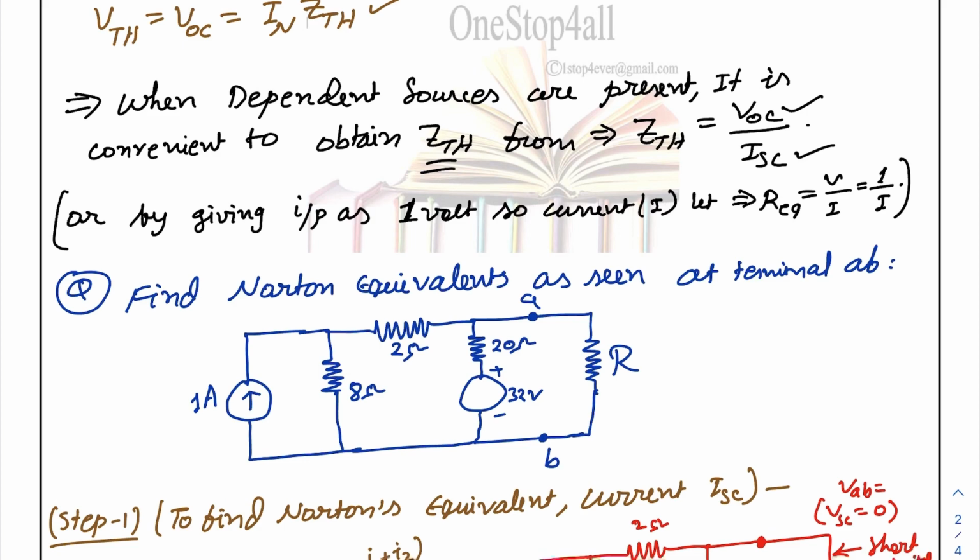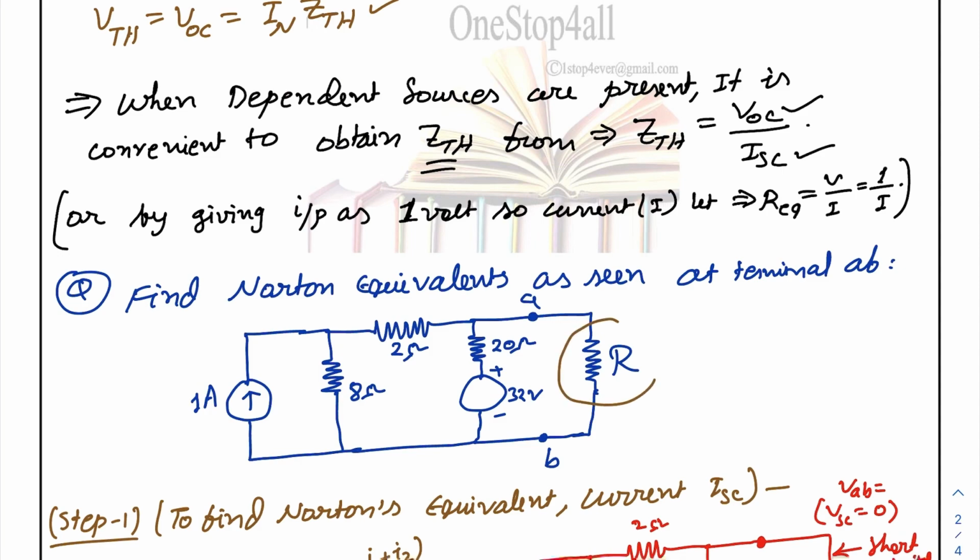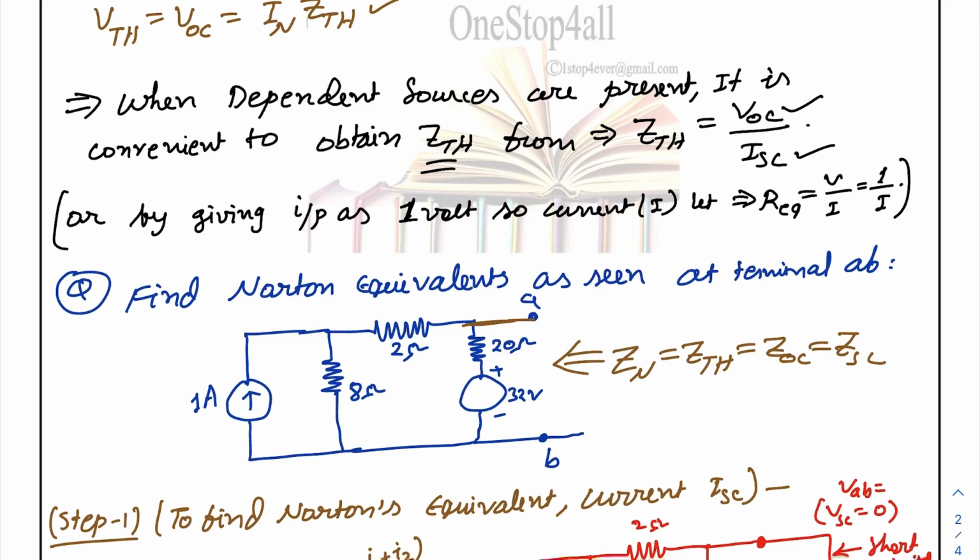जैसा हम लोग ने प्रीवियस लेक्चर में सॉल्व किया है, जो हम लोग ने थेवेनिन इक्विवेलेंट निकाला है, कैसे निकाला था याद है आप लोग को? इट इज़ सिंपल. वी विल रिमूव दिस वन, इसको ओपन सर्किट कर देना है, ठीक है. और यहाँ से ये ZN बोलो या ZTH बोलो या ZOC बोलो या ZSC बोलो, ये सब एक ही टर्म है. नॉर्टन इक्विवेलेंट, थेवेनिन इक्विवेलेंट, ओपन सर्किट इन केस ऑफ थेवेनिन और शॉर्ट सर्किट इन केस ऑफ नॉर्टन, ये सब इम्पीडेंस हम लोग इजीली कैलकुलेट कर सकते हैं यहाँ से लुक करने से.